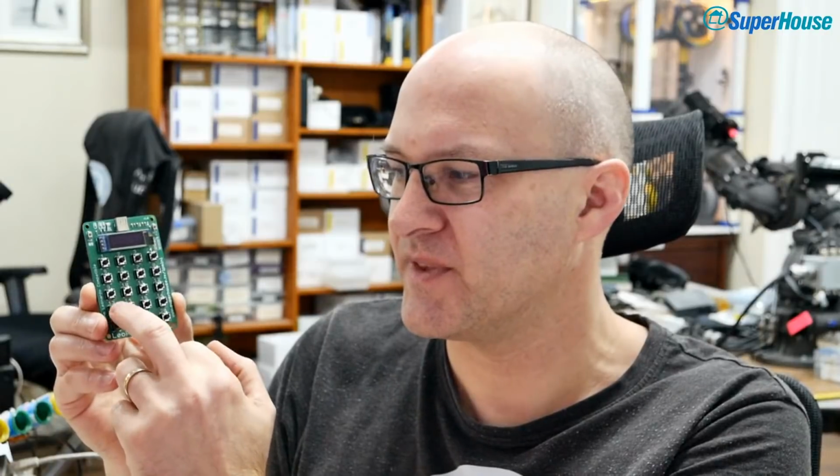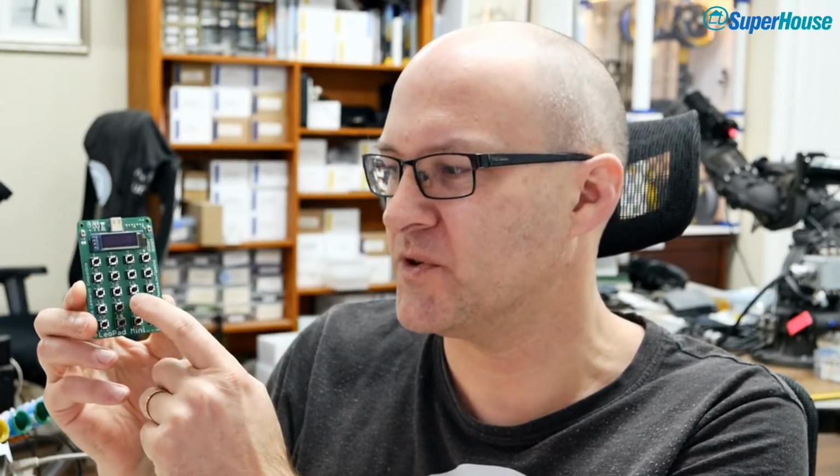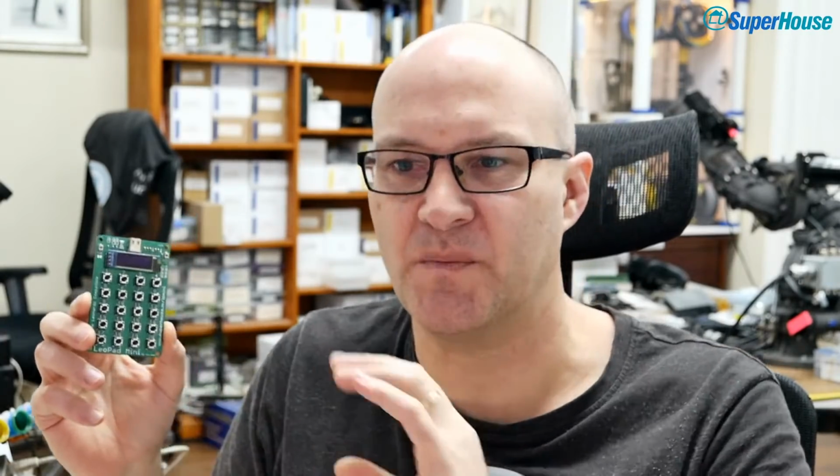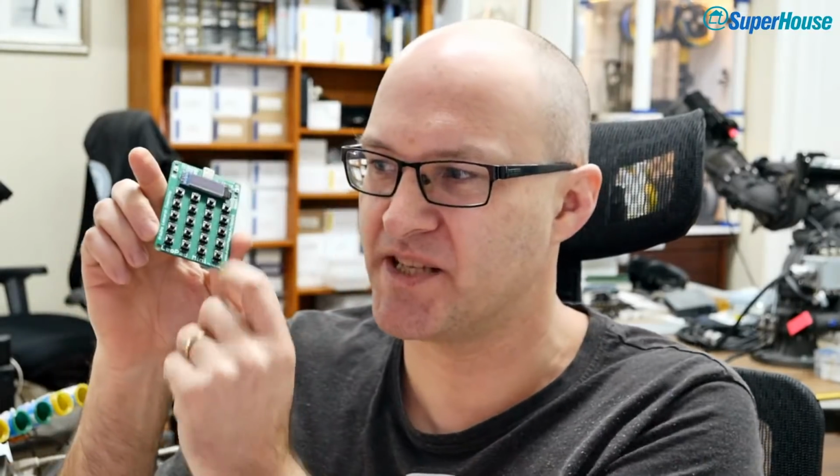And I've got this loaded up with Eagle macros. So what I've got is view schematic, view PCB, and this one here I've just set up right before the live stream. What it does is turn on and off a whole bunch of layers within Eagle, and it brings the focus correctly. It sets the visibility on the silkscreen layer on top of the copper so that you end up with the view like I showed a moment ago. So hopefully, as I'm rushing through these projects, I'll be able to just press that button and the PCB view should reset itself to some kind of a sensible value. Just got to plug that keypad back in, blue tack it back down onto the desk. It's normally stuck there so it can't move.